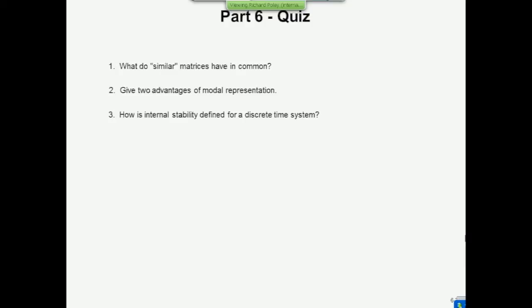What about the eigenvalues? Stable. The eigenvalues must be what? Right, to be less than 1, or if it's Lyapunov stable, it has to be equal to 1 or less than 1. That's right. When is a system? I've just told you this. When is a discrete time system stable? ISL. Remember what that meant? In the sense of Lyapunov, it's stable when the eigenvalues have a magnitude less than or equal to 1, because actually strictly the Lyapunov stability includes asymptotic stability as well.